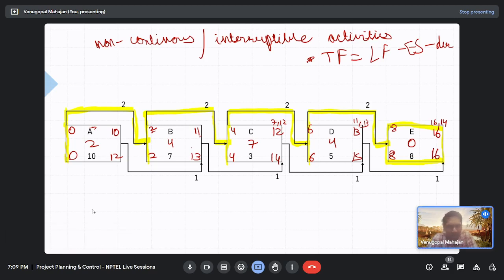Why do you think it is giving you more information than CPM? In CPM, we get the whole activity as critical. During the monitoring process, if our project is getting delayed, we directly change the schedule of that particular activity. But sir, one thing is there: in a CPM it is not possible to check for only the start or only the finish of an activity, because all the relationships are finish to start.